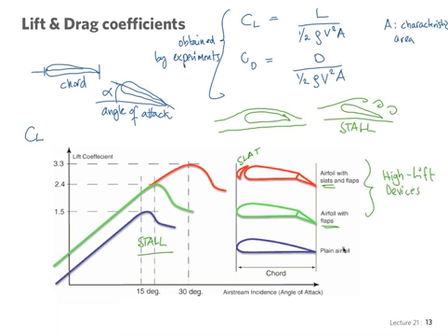We'll return to this again. I'm just introducing some concepts at the moment. We'll return to discuss this in more detail when we concentrate on the force of lift in next class. But the main idea that I wanted to communicate at this point is that lift coefficient and drag coefficient are going to be provided through experiments, because obtaining the aerodynamic forces exactly would be very difficult. It would require us to know the pressure and wall shear stress at every point.